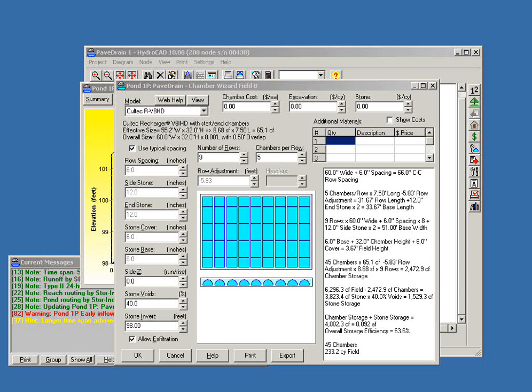And let's say something really drastic does happen to Pavedrain. You have a truck tip over and dump half of its load of sand on it, and you can't sweep it up, and it just doesn't seem to be performing as well. And let's say it's been in for a decade. You could expose the cables and pick a mat back up, clean your aggregate bedding layer, and then put all that material right back in, same cleaned rock, and the same Pavedrain mats could go right back in, and voila, you've got a whole brand new impervious surface, allowing for infiltration.